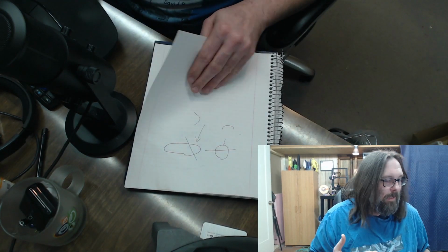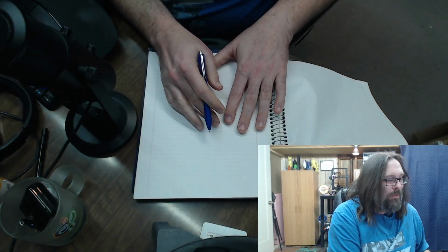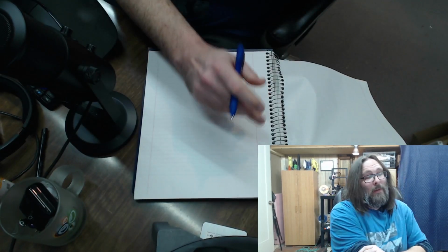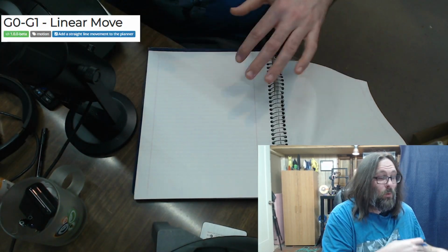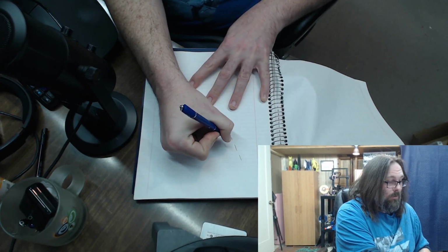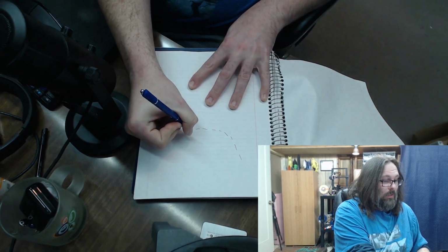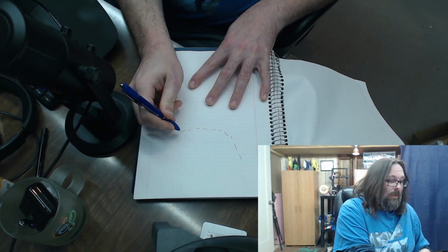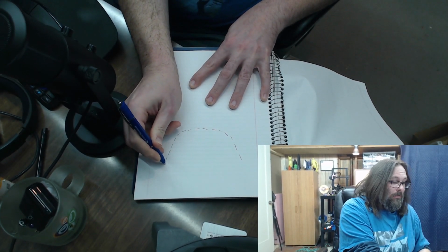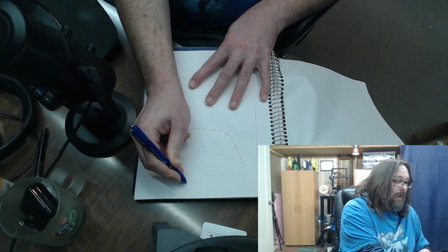So let's turn the page, literally. When we usually get a 3D print, the files that are created from the slicer use move commands, either G0 or G1, and that gives us straight segmented lines. So for example, if we look here, I'm just drawing a few segments of some straight lines, or as straight as my hand can draw, and eventually I can circle back with straight lines and get segments that semi-match.